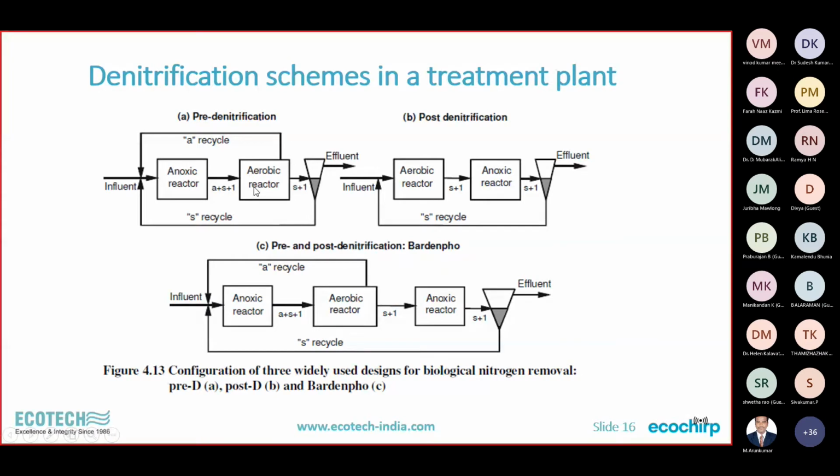And 4Q recycle rate, as you all know, in an MBR, it was an MBR system, in fact, an MBR STP, 4Q is the normal recycle rate. So we didn't have to bother much about excess energy consumption. The MBR technology itself is excellent, well suited for denitrification, because even without denitrification, it calls for 4Q recycle. So we are not expending extra energy just because of the denitrification stage.